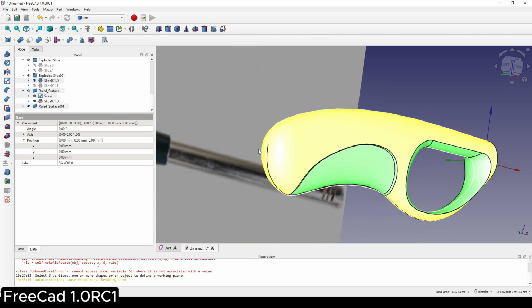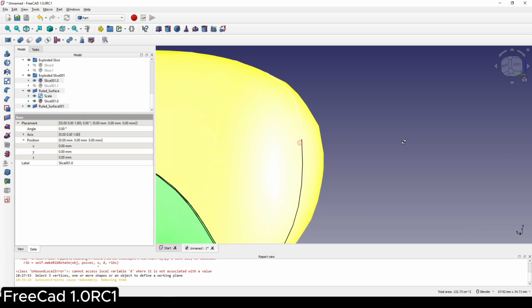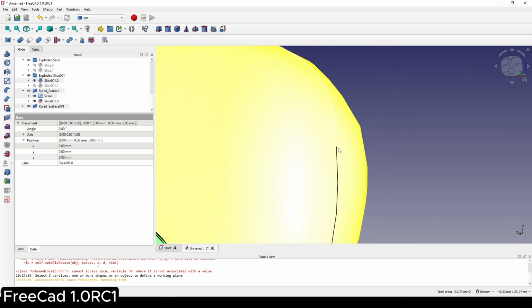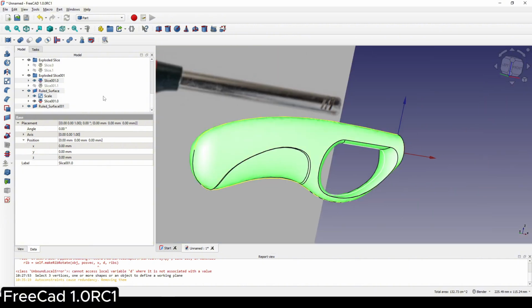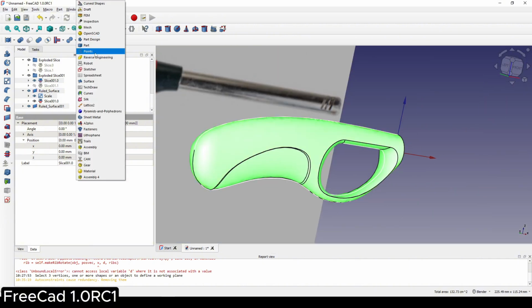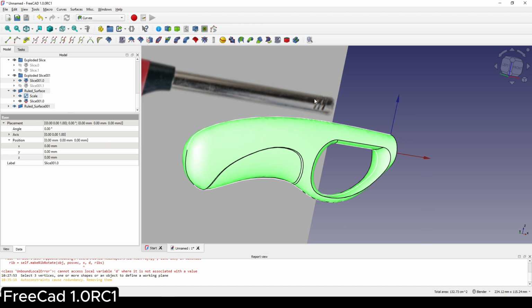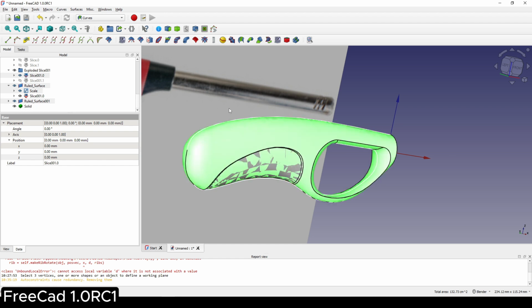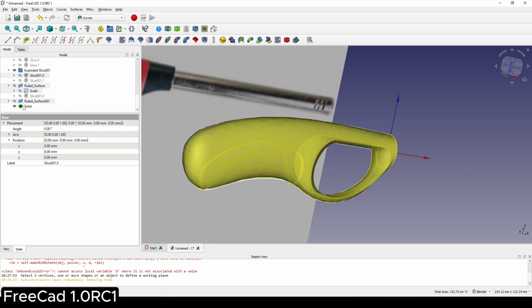And the last one in here, very small one. Okay, and then I go to the curve workbench. And I click on parametric solid. Click on it. Now we have a new solid. And I hit spacebar to hide everything except for the solid.